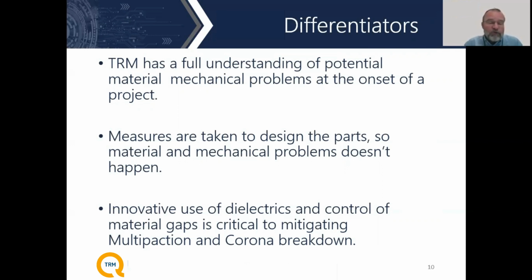And the other important part, not to forget our discussion from last time about multipaction corona. Multipaction corona is a very real phenomenon. It can happen at very low voltages in a vacuum, and therefore virtually every design has to be cognizant of the fact that this phenomenon can happen, and it will happen if you're not careful. I think the one thing I also want to bring up a little bit here.